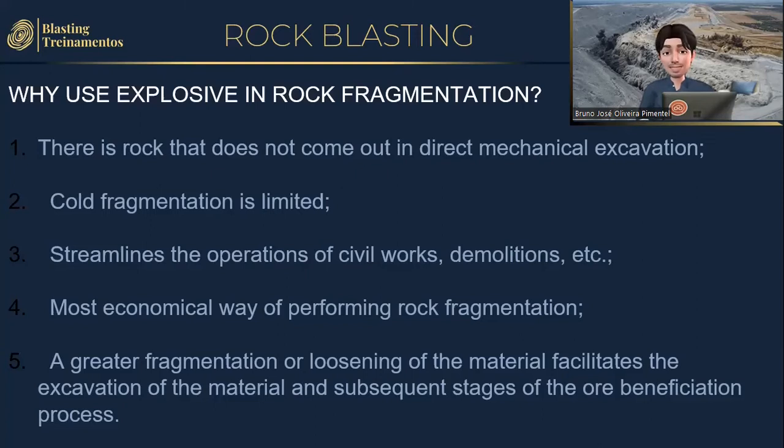The third point is that through rock blasting with explosives, we speed up a series of works and demolitions, because in order to remove this rock, to fragment it without the use of explosives, the process would be very expensive and slow. For example, the demolition of a building, if you need to demolish it mechanically, you will have to go step by step, and that takes days and even months. But with explosives, after everything is prepared, in a few seconds we have the demolition of a building. In the same way, crushing a rock with hydraulic or mechanical equipment, for example with a breaker, or even with cold fragmentation, would take a long time and could cost much more and be less efficient than through the use of explosives.